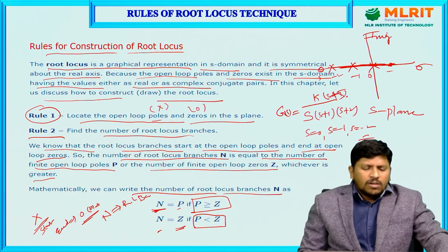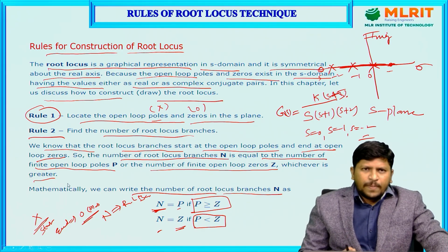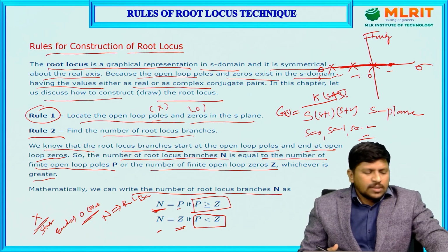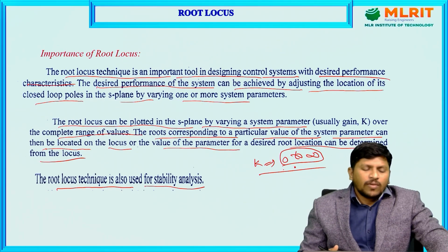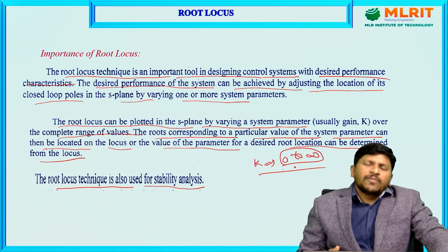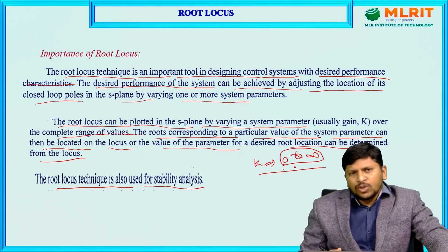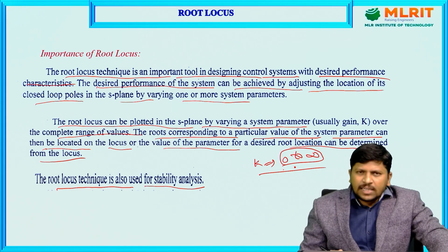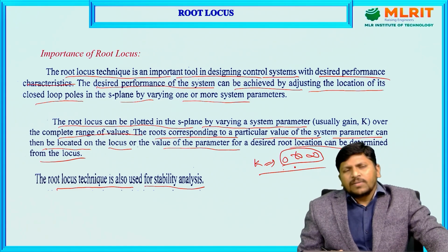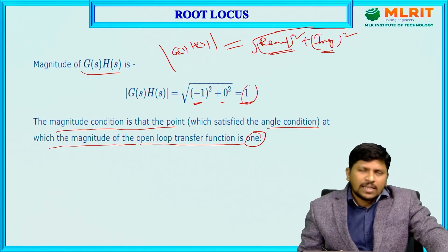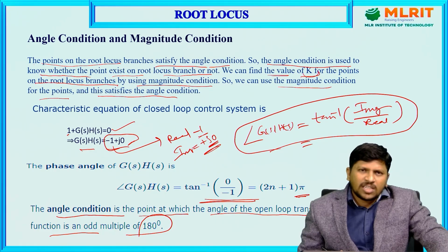I hope you understand how to follow the rules to draw the root locus, and also the importance of root locus for higher order polynomial equations. Locating poles or roots on the S plane is easy using the root locus technique, and it is also useful for stability analysis of any system, along with magnitude and phase calculation from the characteristic equation.